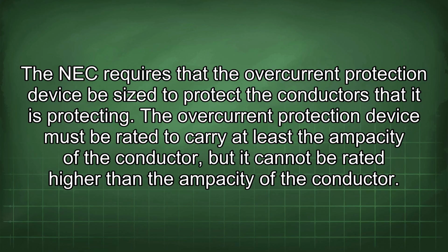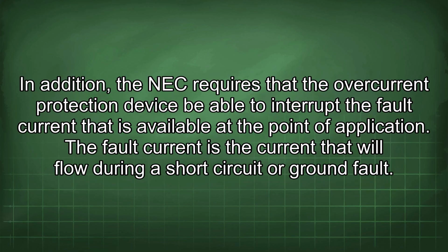The overcurrent protection device must be rated to carry at least the ampacity of the conductor, but it cannot be rated higher than the ampacity of the conductor. In addition, the NEC requires that the overcurrent protection device be able to interrupt the fault current that is available at the point of application.